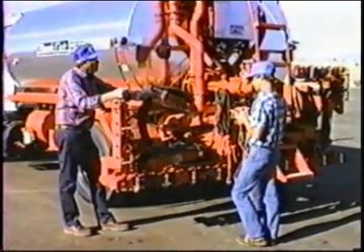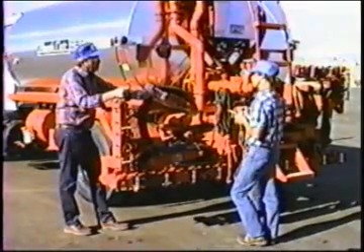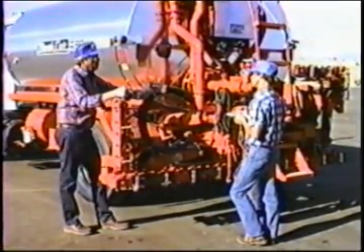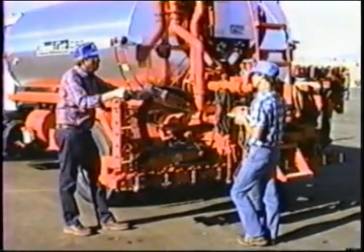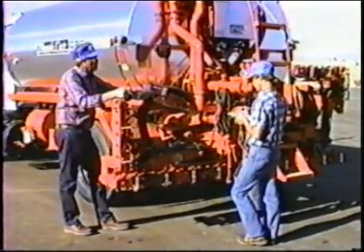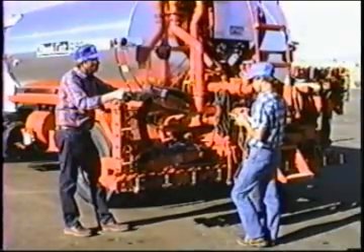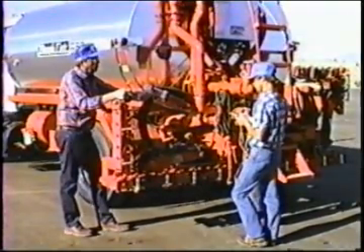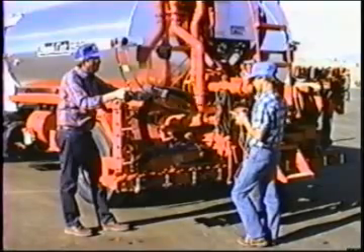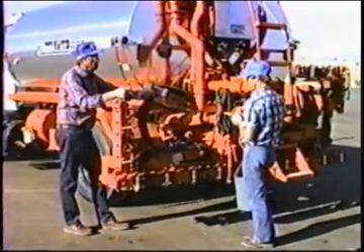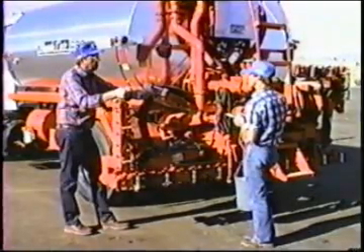Set the bypass valve at 8 pounds. Okay, now notice on the slide rule that the only speed that 8 psi puts down 0.25 gallon per square yard through number 3 nozzles is 400 feet per minute. Right. So that means that if we are using the bypass valve, we have to run a constant speed. That is, we have to maintain that travel speed.